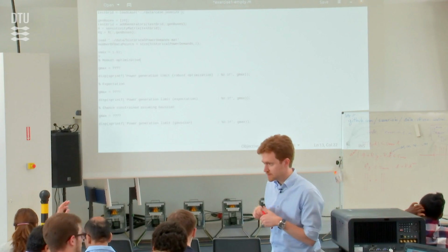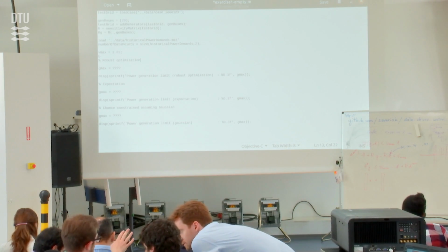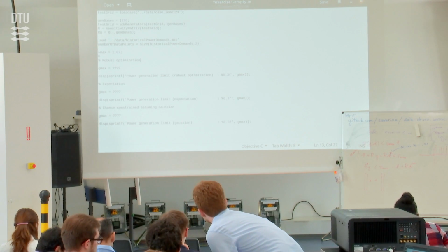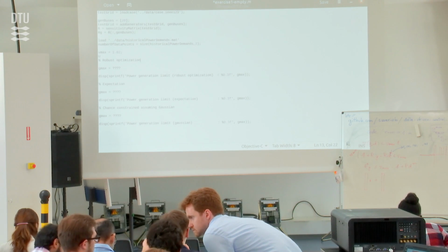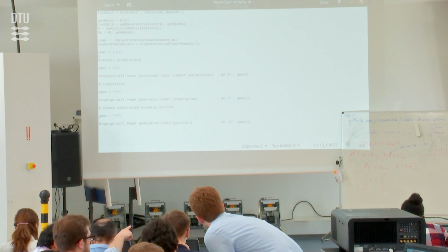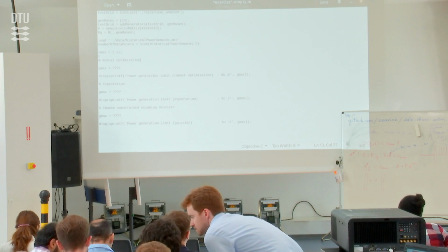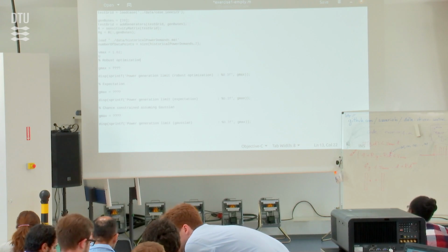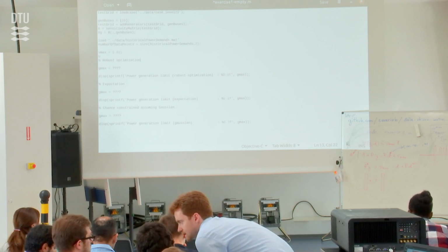Yeah. On the first one, we don't need to actually check the condition because we have just one generation, so we can just find the maximum. Yes. So we use this condition actually to find the generations, right, from the Z1 plus R multiplied. Correct. Yes. But when we do so, this is V max minus 1s, but we also have to multiply from the left-hand side by the RG inverse matrix, right? Yes. Well, RG is only a vector, so you have to do the inverse element-wise.